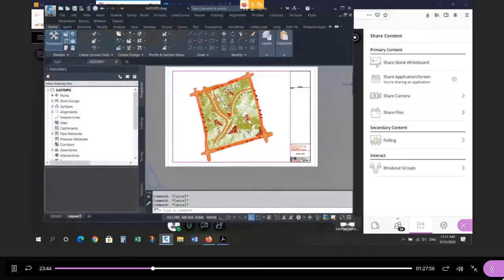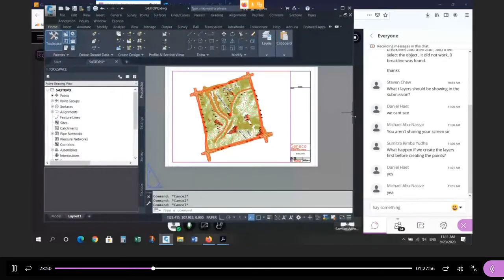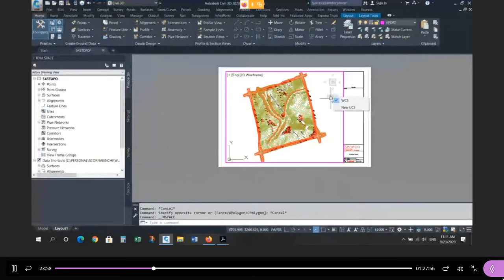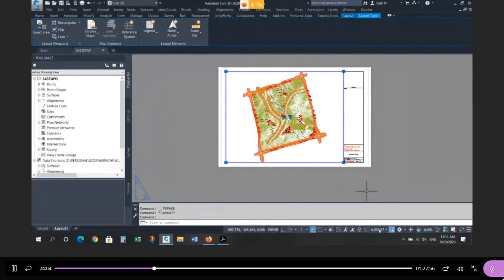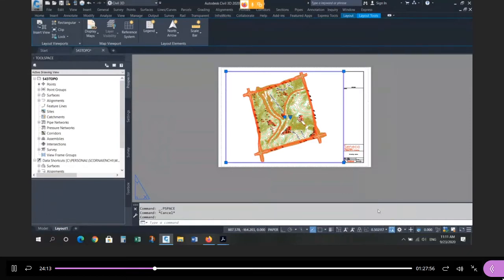So here we are in AutoCAD. Again, if you want to establish scale, when you create this, it always zooms extents. So if I go in here and type ZE, enter, if you look at that, when you first create it, it's got a weird scale. It wants to be 0.5. It has to be exactly 0.5, which is half of 1,000, 2,000. So I'm going to choose 2,000. Okay, so that's a true scale of 1 to 2,000.